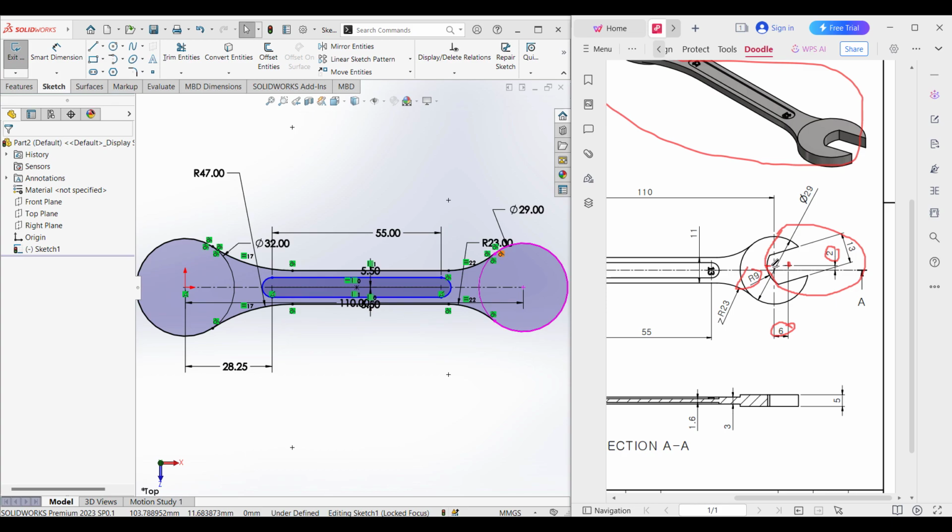So then I will draw a horizontal center line here, then I'll draw an inclined center line here, and I'll angle them to 15 degree. And from that inclined line, I will offset these two lines, and these two lines have a total distance of 13 unit, so the half distance will be 13 divided by 2 unit. Then I will trim the extra portion.